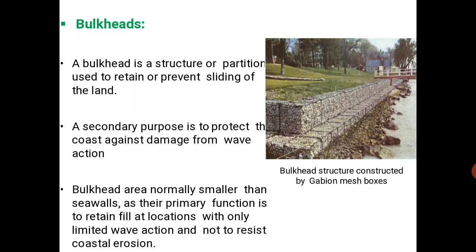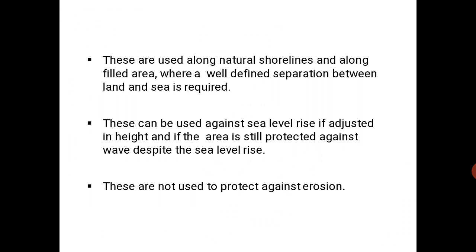These are used along natural shorelines and along filled areas where a well-defined separation between land and sea is required. These can be used against sea level rise if adjusted in height, and if the area is still protected against waves despite the sea level rise. These are not used to protect against erosion.